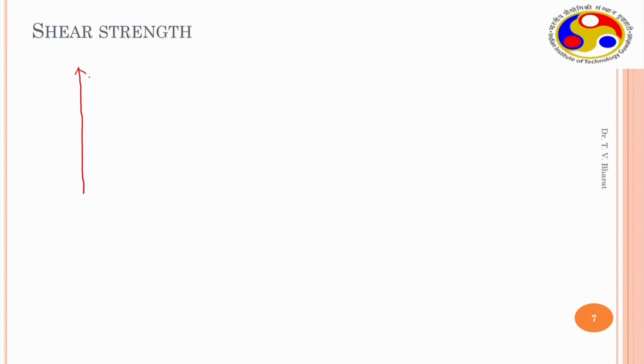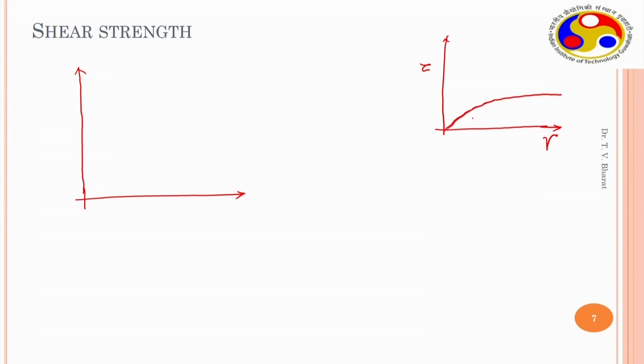So, when they plotted, generally in our direct shear tests, we obtain shear stress versus shear strain, written as gamma, and the stress versus strain relationships for NC soils look somewhat like this, and for OC soils it appears somewhat like this, and this is called strain hardening behavior.